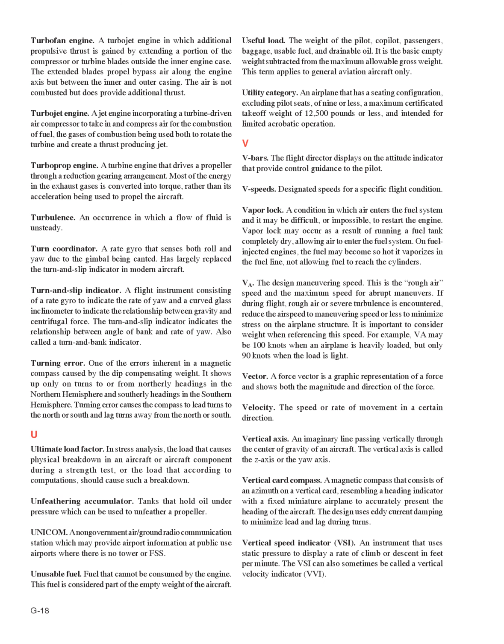Turbofan engine. A turbojet engine in which additional propulsive thrust is gained by extending a portion of the compressor or turbine blades outside the inner engine case. The extended blades propel bypass air along the engine axis but between the inner and outer casing. The air is not combusted but does provide additional thrust. Turbojet engine. A jet engine incorporating a turbine-driven air compressor to take in and compress air for the combustion of fuel, the gases of combustion being used both to rotate the turbine and create a thrust-producing jet.